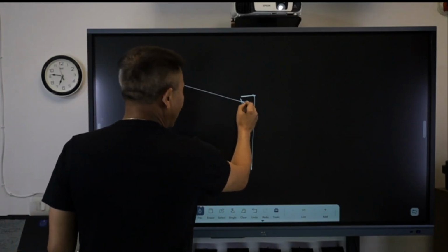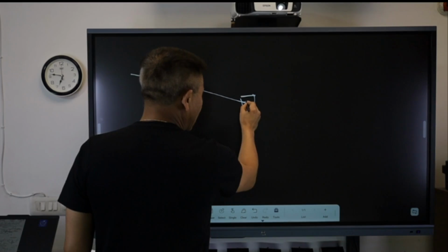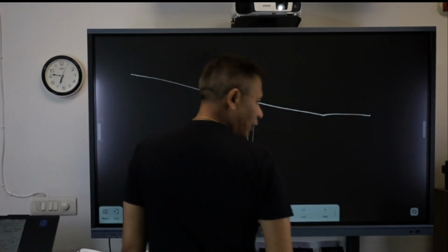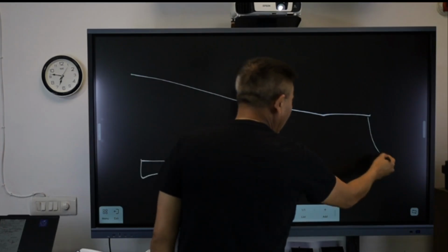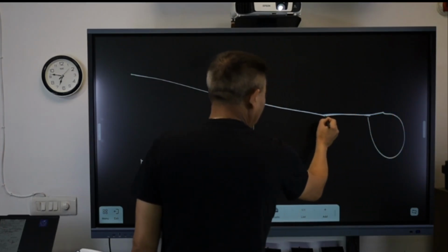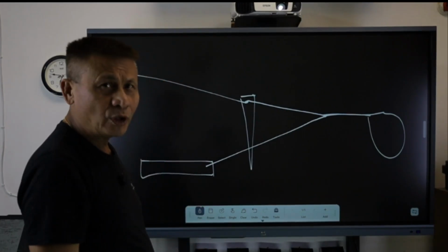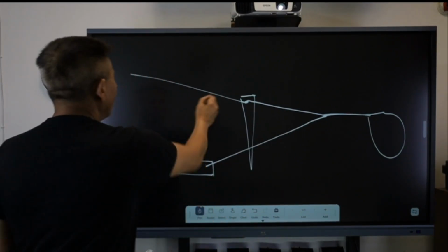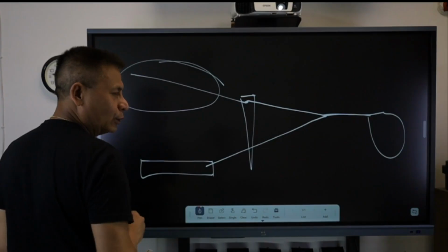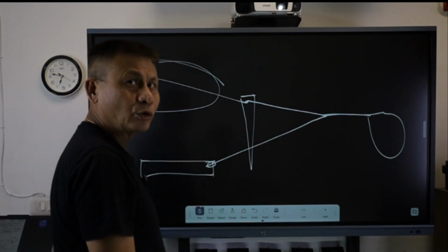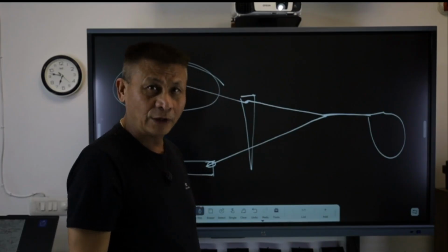Thereafter, I have to follow a series of procedures like going on a track like this, leveling out at a certain point of time, then carrying out a reciprocal turn, and then coming over here and commencing descent and landing. So how do we transition from this en route mode right up to the landing is done through this instrument approach procedure.